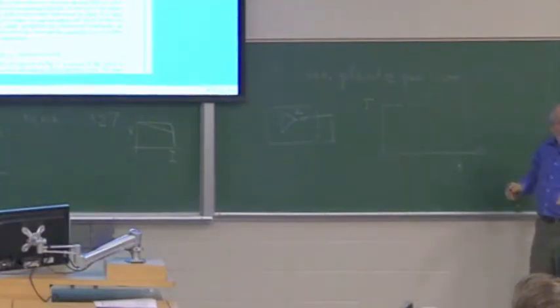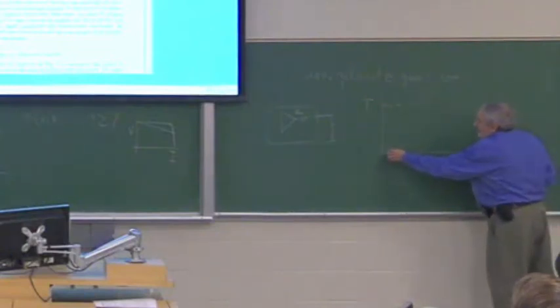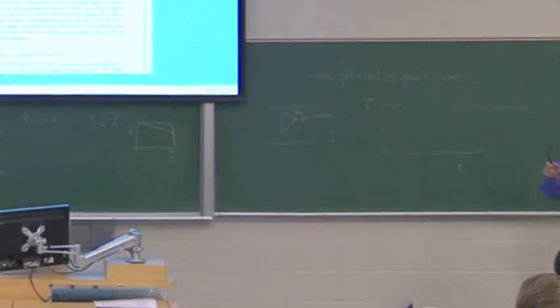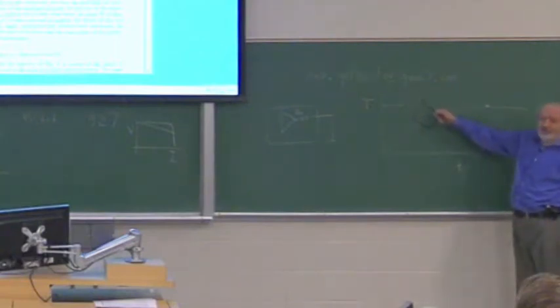So you have to give it less power so the temperature will stabilize where you want. Okay? And that's how all open loop ovens work. You just give them just enough power so the temperature stabilizes. Say the older version of soldering irons. They just had enough power to get a certain temperature and it stabilized. But it takes a long time. And if you give it too much power, it will get too hot.